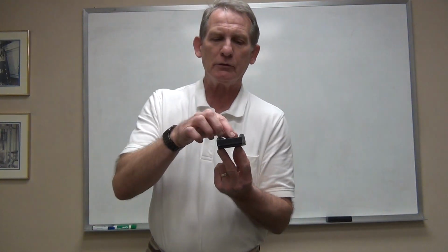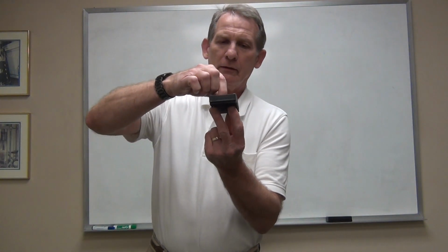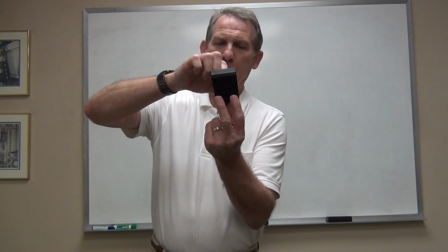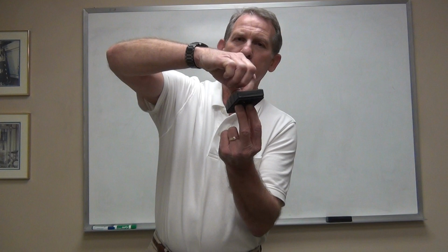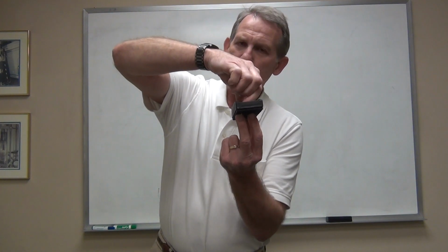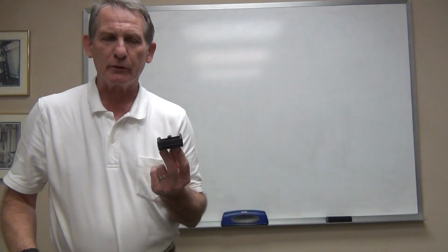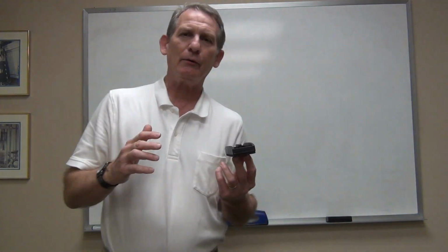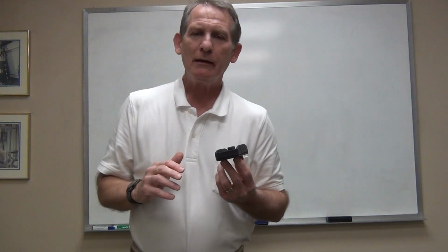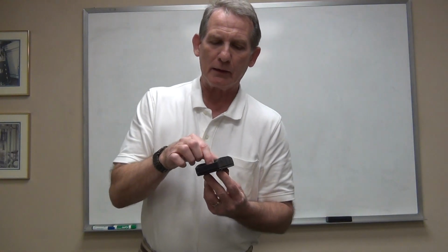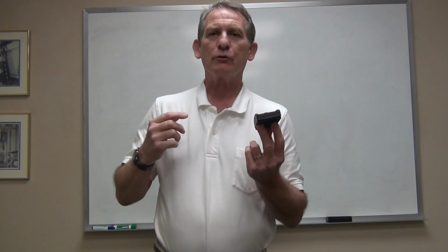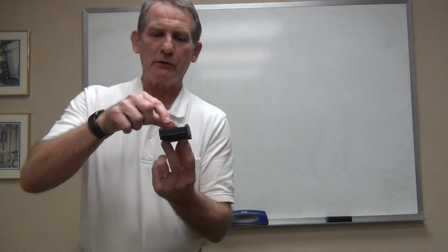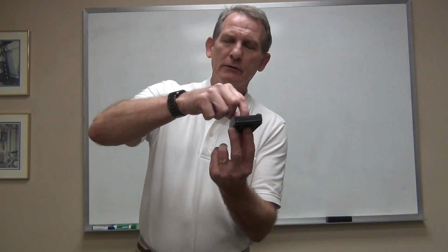Let's look at the rotations. I can't do this, I can't pitch, I can't roll, but I can yaw. So I've still got that degree of freedom. What if I really want to lock this thing down in 3D space? I have to start adding additional datums. I have these 3 datums. Let's say I want to tackle the translational degrees of freedom that I still have left, the fore and aft, side to side.